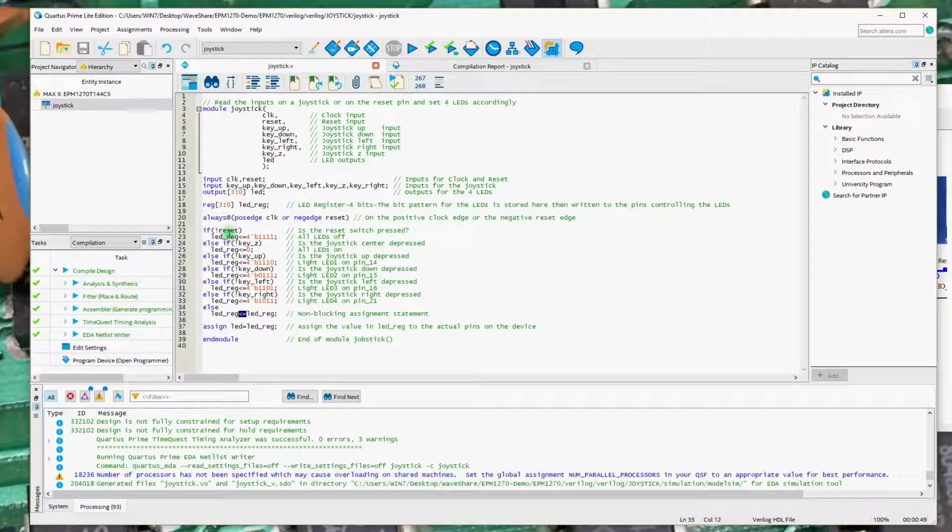this is being implemented in hardware. And you can get into race conditions. These things are basically happening at the same time, I guess is a way of saying it, in the hardware design, in how this gets evaluated in the implementation in the CPLD. And blocking and non-blocking control when things happen. I encourage you strongly to do some reading and explore blocking and non-blocking in Verilog. It's not something I've really got my brain wrapped around, and I don't think in this case it's required.